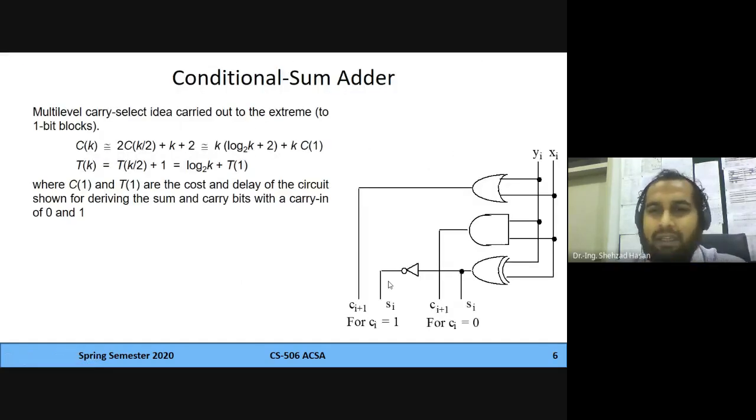So this is another adder, conditional sum adder. So it's even faster than the carry select adder because you're talking about doing it without any ripples. Okay, so this design is also good, and you can implement a fast adder using this. But when you're talking about fast adders, normally there are parallel adders, and there are different techniques that we are not going to consider. If you are going to go for a course of parallel processing, then we discuss those adders there, how to do parallel additions, but not over here. So we are just discussing simple adders in this case, right?